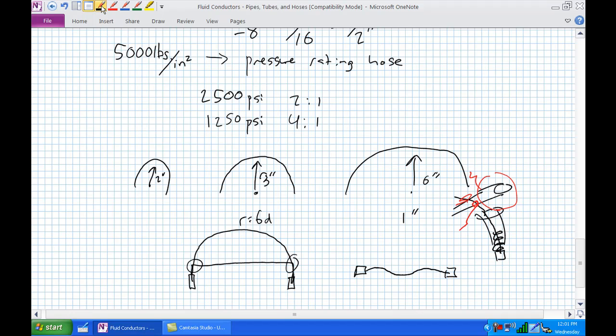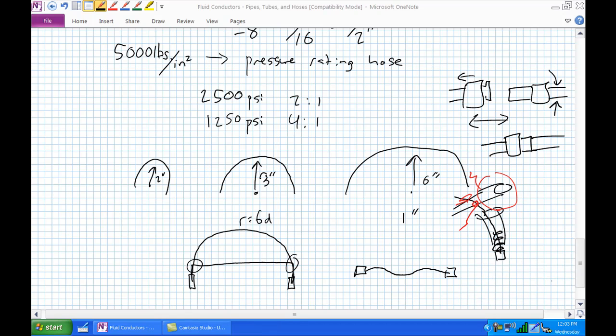Okay, so obviously your quick disconnects, we've already seen these things a bunch. There's the female end, there's the male end, and these are crimped onto a hose using a hose crimper. And what you want to do is pull that back, insert them. When it clicks down, tug on it on either end, just to make sure that those guys are properly connected. Because the last thing you want to do is be troubleshooting something that does not have fluid flow or is not receiving any pressure or fluid flow, and be troubleshooting a component when something's not properly connected.